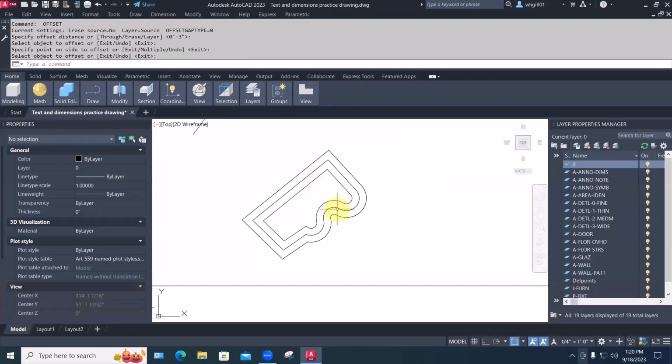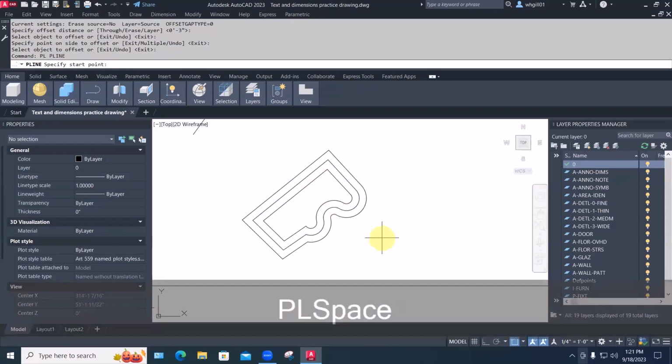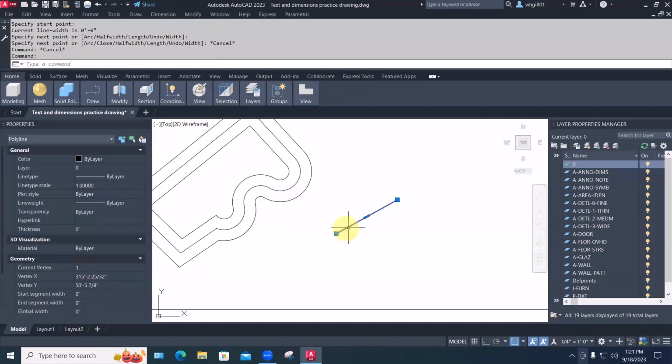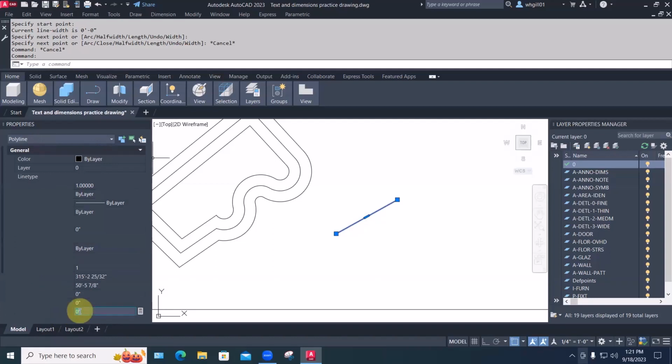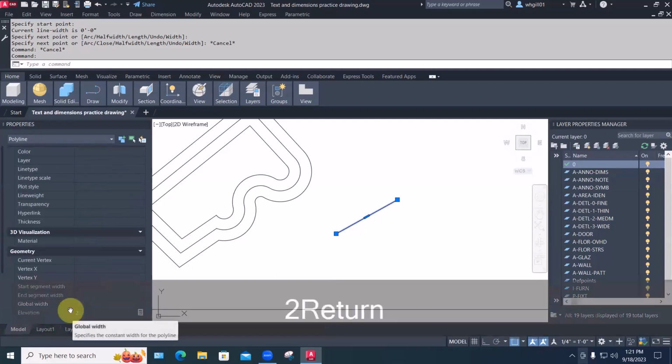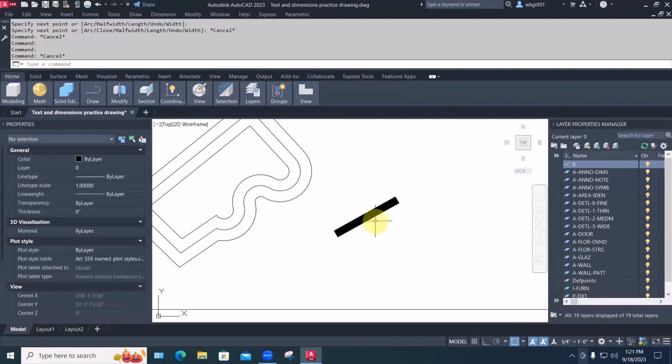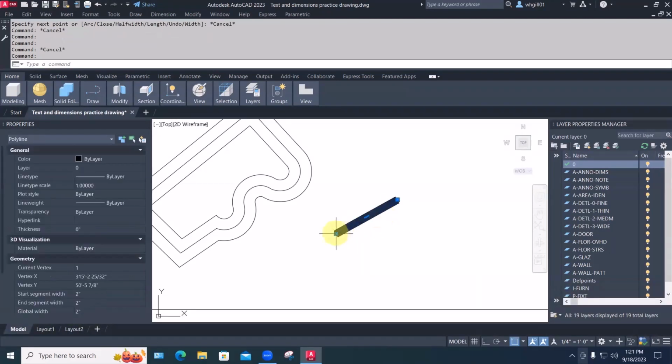as desired. A polyline, let me just draw a straight one, can have, if we need to make some really fat lines in our drawing for whatever reason, I mean, for graphic design on the title page or whatever, we can just select it and in properties, go down and change its global width to say 2 inches. And the whole thing just becomes a fat 2-inch thing. It still is only defined by 2 points. It's not like I've got 4. It's not a rectangle. It's still a vector. It's just a fat vector.